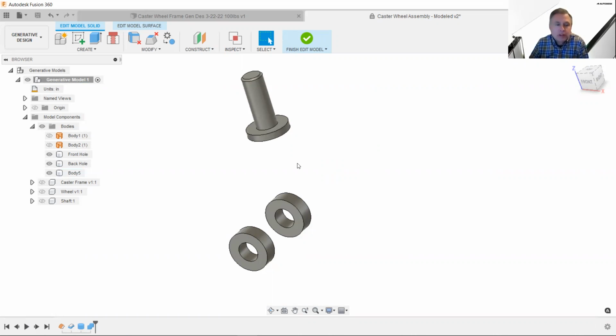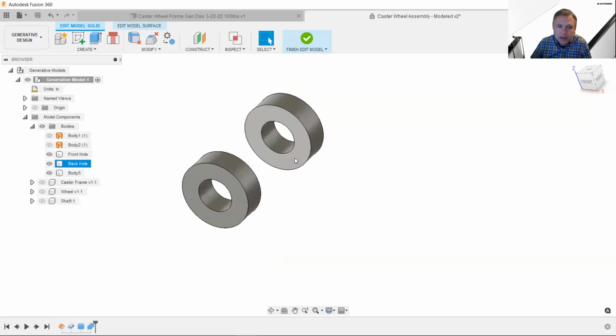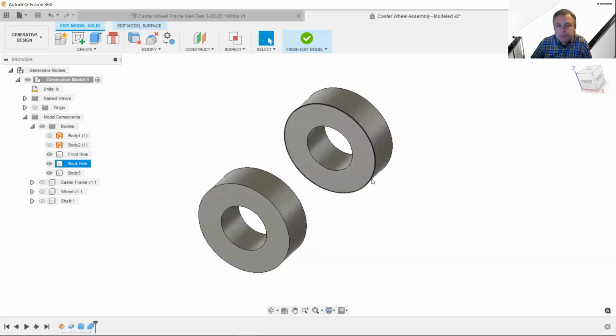So now let's take a look at our obstacles. So again, obstacles, this is going to be the area which some people refer to as keep out. Do not add geometry here, right? And as we saw in the video, what generative design does is it's connecting the preserved geometries together. That makes sense to everybody? Kind of where we're going with this long term? All right, so what I'd like everyone to do is zoom up on those bottom 2 cylinders.